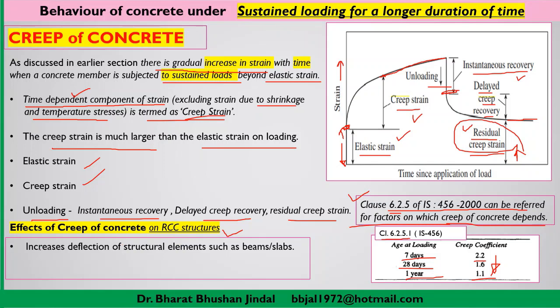The very first and very important point is, when you design any RCC structure, you will first of all be interested in how much deflection will occur in the member due to the loading. So another effect of creep on concrete is that it will increase the deflection of structural elements such as beams and slabs.